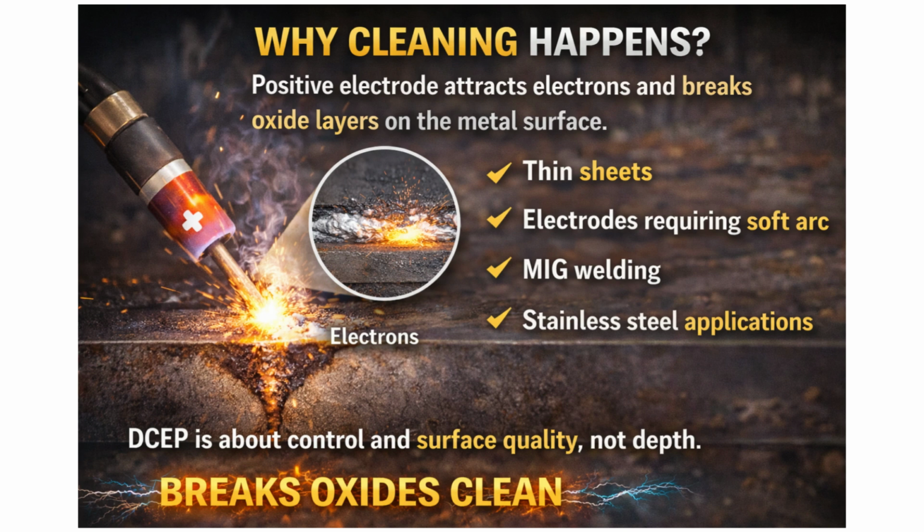Where DCEP is used: thin sheets, electrodes requiring a soft arc, MIG welding, stainless steel applications. Key idea: DCEP is about control and surface quality, not depth.